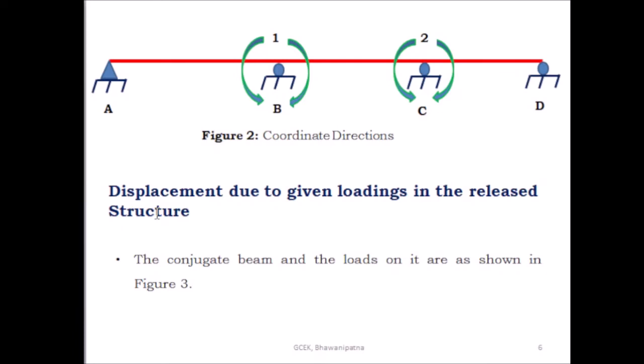You have to find out the displacement due to the given loading in the released structure. Using the conjugate beam method, you can find out the displacement due to the given loading in the released structure.